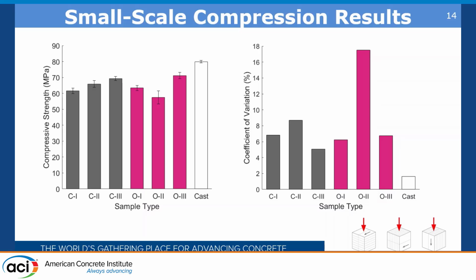In reference to how our different tests perform, our closed toolpath cubes first show slight anisotropic properties, with a 10% reduction in strength from our parallel orientation 3 loading to our perpendicular orientation 1 loading. But given that our mix is relatively strong, reaching 60 to 70 megapascals, 10% isn't that noticeable as far as anisotropic properties go.